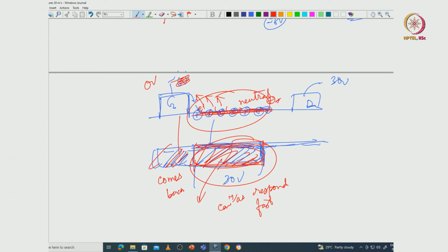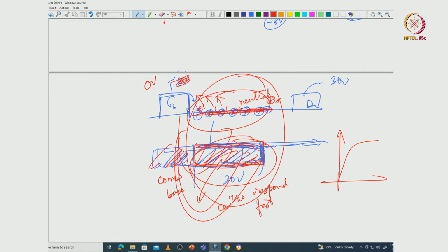Secondly, there is also the buffer, where the field lines penetrate inside; there is carbon doping, iron doping, etc. So these buffer traps, dislocations, all these defects, etc. may also capture electrons, and they may not be able to release them as fast. Because of both of these phenomena, this part will have a lag, it will take some time to come back, and that is why, as opposed to the cold fed condition, in your drain lag condition the current will collapse like that. This is a collapse that is happening.